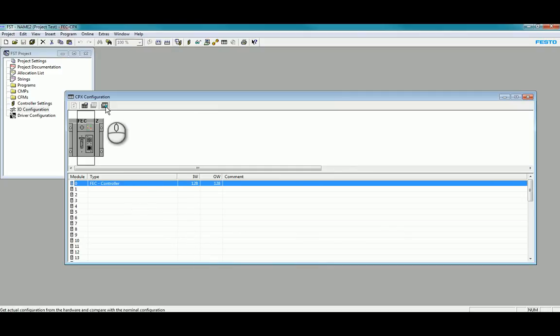At that point, you just need to make sure your input address and your output address are at the appropriate numbers, usually 0 and 0, and then 1 and 1, and making sure if there are any analog connections for either the input word or the output word, that they're not stored currently at 0 or 1, and you could put them at a nominal range of, for instance, 64.